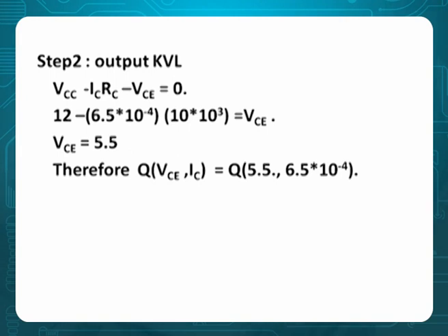In this process, understand that first IB comes. IB is also called a quiescent value, but it is not called the quiescent point. VBE is also called a quiescent value, but not the quiescent point. So when they say quiescent values, all these 4 values are called quiescent values: IB, VBE, IC, VC. But only VC and IC is called the quiescent point.